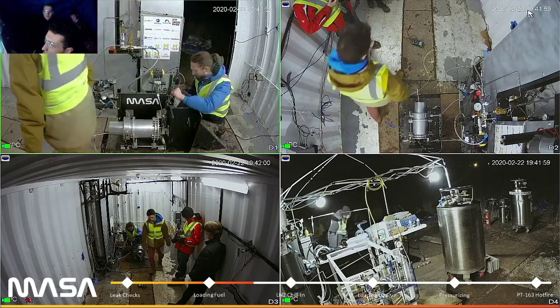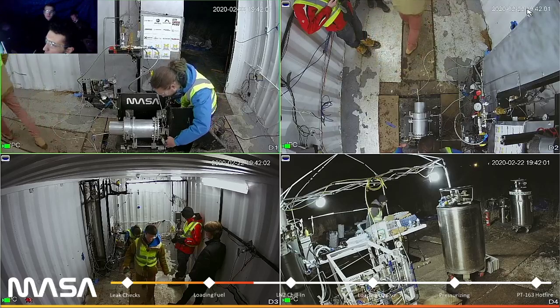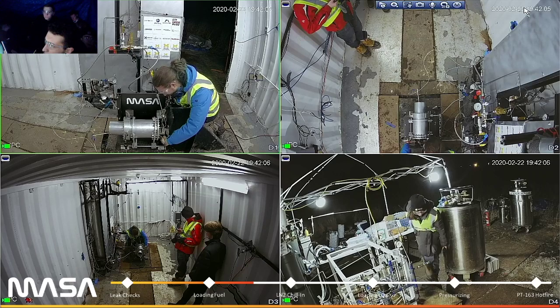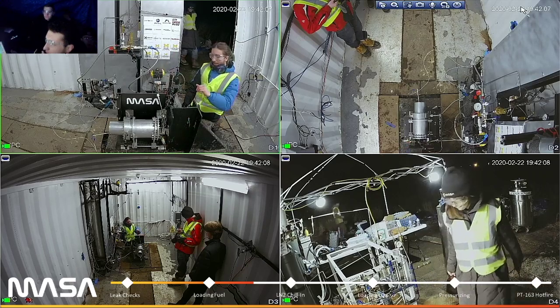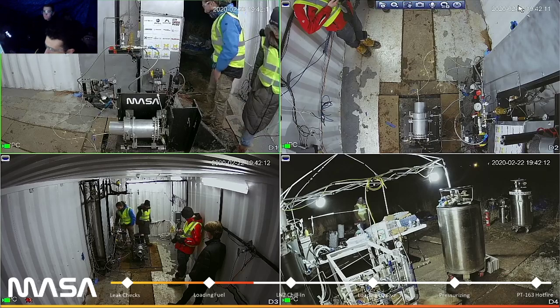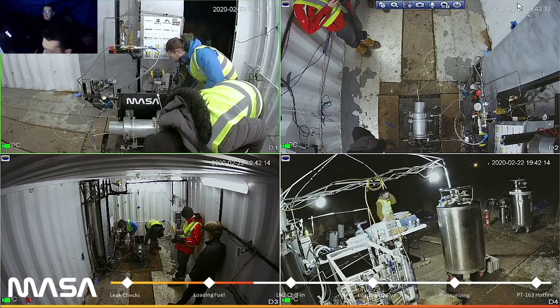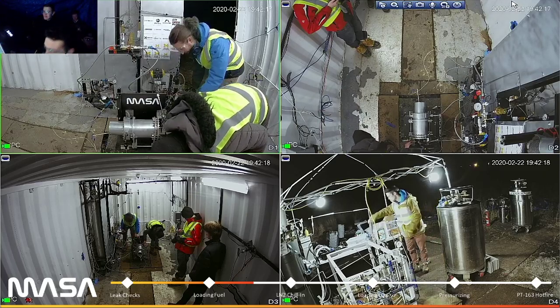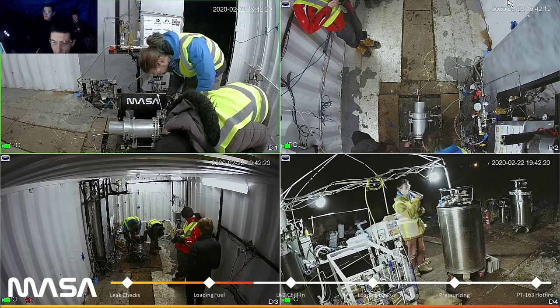All right, what kind of data do you get from the test stand? We get a lot of data from the test stand. Some of the most critical things are the thrust measurements. We have 3 load cells behind the engine which measure thrust. We basically sum the values from the 3 load cells to get total thrust. That's one of the most crucial measurements that we take.